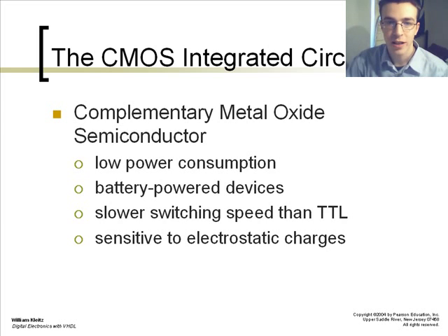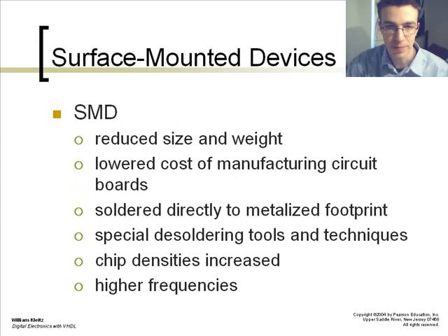And you have the CMOS integrated circuit types. These are mostly used in industry. They are low power consumption devices and battery powered devices. For educational purposes, however, you will mostly use your TTL style chips. These have a faster switching speed, and take a little more power. However, to understand the concepts and to see your values change on your oscilloscopes, these are much easier to determine.